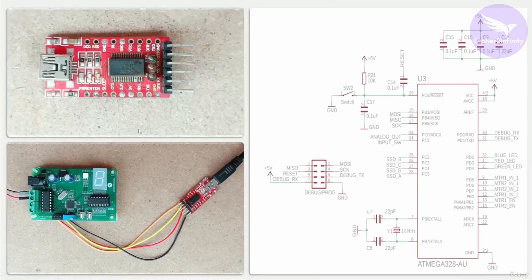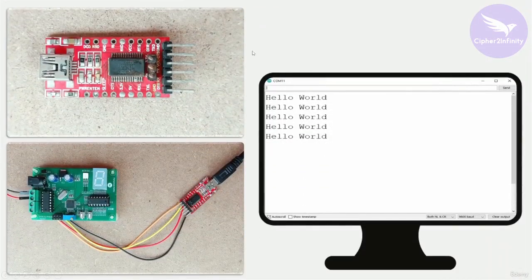So now let me show you one image, and from that image, you will get more clarity about what I was talking about. Whenever you have to check the data sent by the controller on the TX pin of the UART interface on the computer, first of all, you have to open a terminal window, or it can be any type of terminal software.